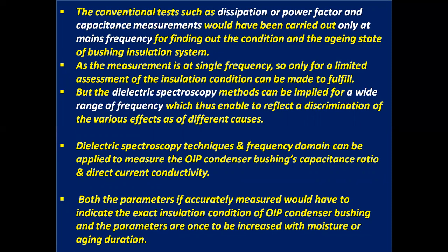As the measurement is at a single frequency, only a limited assessment of the insulation condition can be made. But dielectric spectroscopy methods can be employed over a wide range of frequency, which enables a discrimination of the various effects arising from different causes.